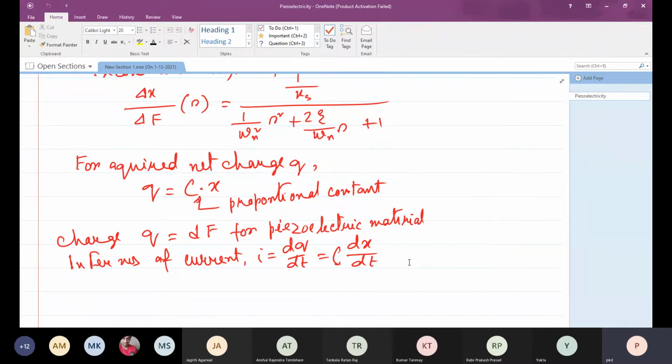As such, the electrical equivalent of the piezoelectric crystal: if we neglect the loss coefficient and take it as an ideal form, it would be a charge reservoir and behave like a capacitor, because basically piezoelectric is made of dielectric material.